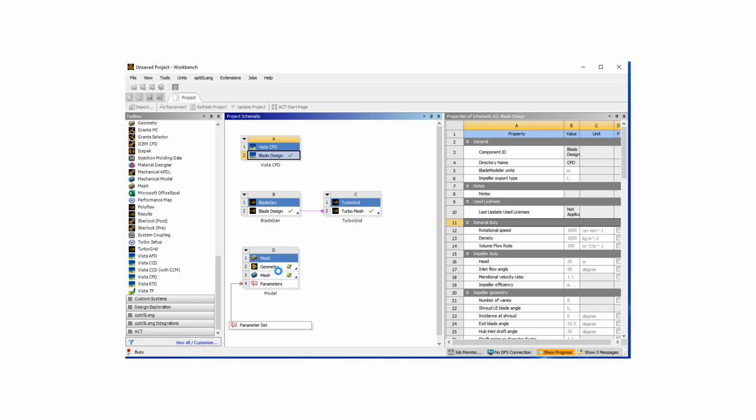and then it will automatically go to the mesher and generate the mesh for us without us having to provide any inputs. So right now it's building the geometry. You see the green check mark, which is good news. The geometry is cleanly built, and currently it is working on the meshing. In the background, it actually is using, like I mentioned, workbench meshing with automated settings for a volute mesh.